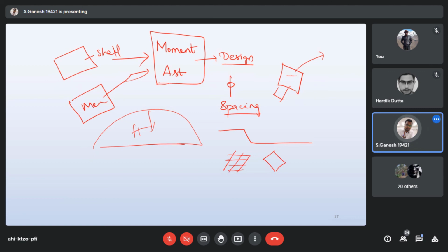Okay, Yuvraj asks: after meshing, the beam supporting the slab also gets divided into small elements. Can we analyze that beam as such? Yeah, see, that is not a beam, that is meshing only. So that will take care of the stress distribution concept. I'll show you that meshing. It is a meshing concept, not a beam concept.